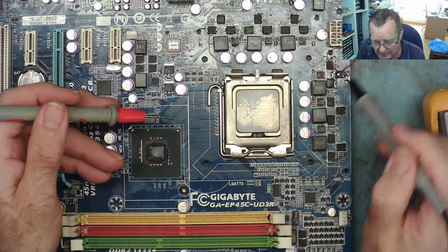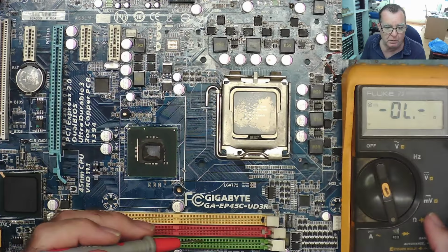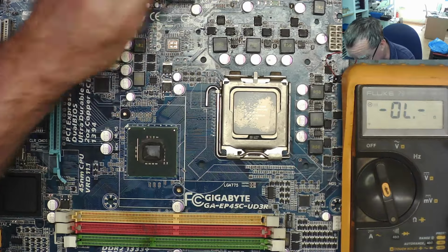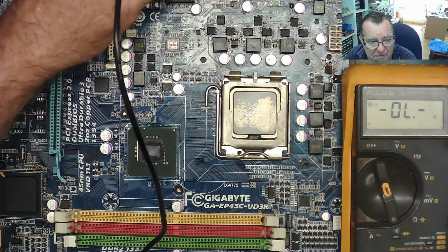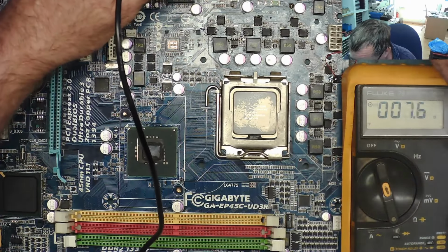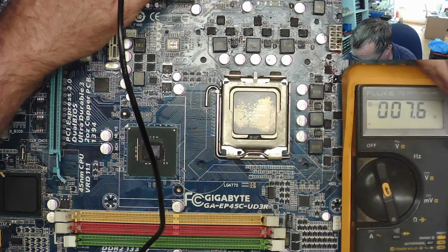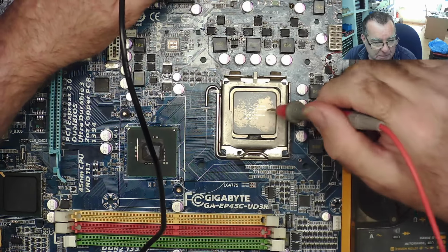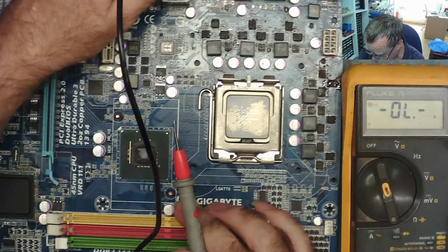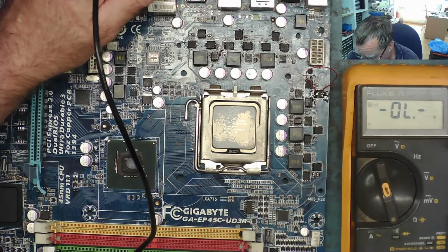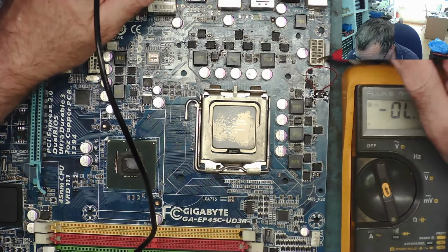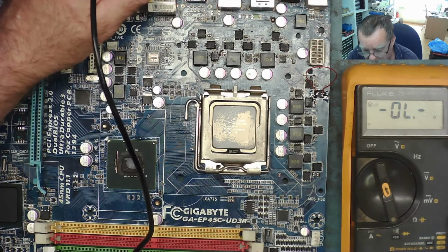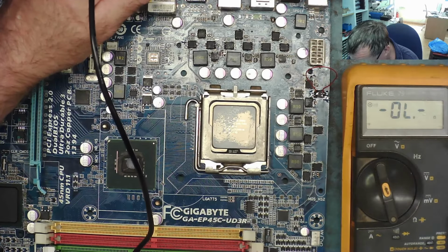Yeah. And what I've done is I've simulated a fault by putting a short circuit on this one, on this phase. Now, if we look with our ohm meter at our VRM, and we compare first of all from 12 volts in to ground, so here's your 12 volts in, you'll see we're reading about 7 ohms, yeah? And that is the resistance of the CPU. So if we were to switch this on, the 12 volts would go directly into the CPU. Hopefully the ATX power supply would trip out, but possibly not before damaging some things, yeah?